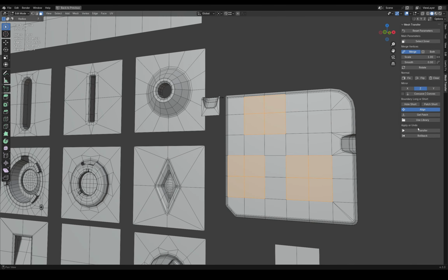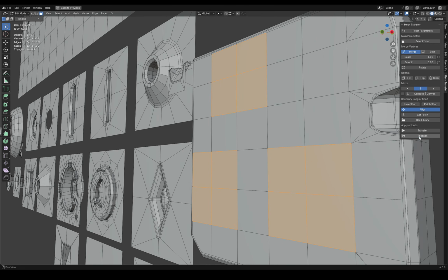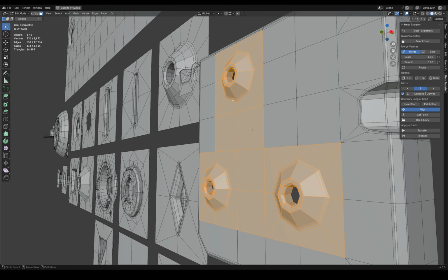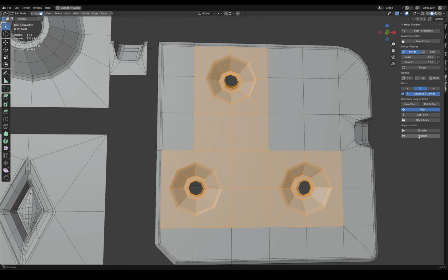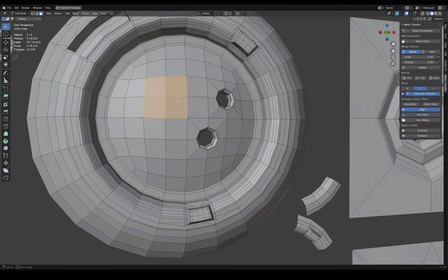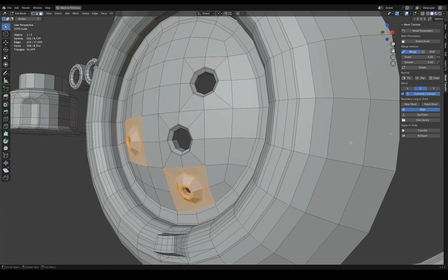The Concave and Convex parameter helps to turn all meshes in one direction, taking into account the shape. This works correctly if you have a plane, but when the shape is semicircular or uneven, copies can stand in different directions, so it is better to insert them separately in such cases. If the object has an uneven surface, as I already said, insert the mesh separately. This will eliminate the problem with the direction.